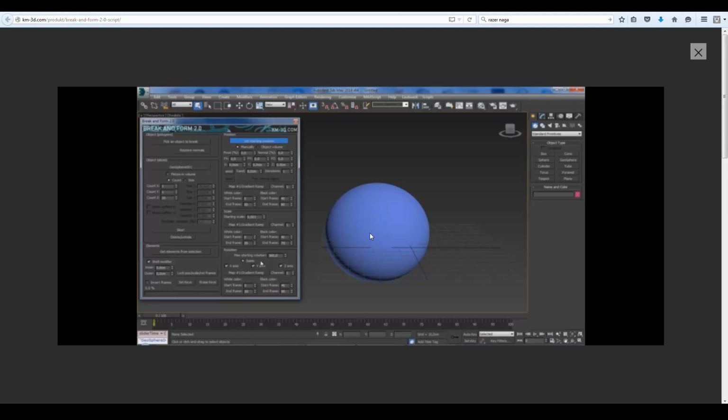By the way, I was not looking into particles, but at something that can create an animation on the translation, rotation, and scale nodes. If you have this kind of animation on an object basis, you can export it as a simple animation, not a cached animation. You can animate the translation, rotation, and scale nodes and export that information directly inside Maya from 3ds Max using the Send To button. So it's a pretty straightforward procedure, and that's what I was looking for.